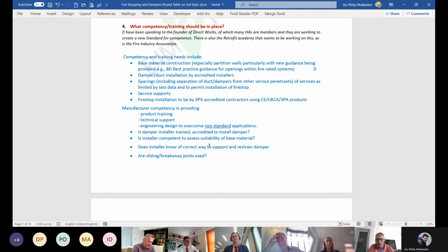That's my practical experience. So therefore, when Howell is saying that the fire stopping would be designed, presumably by an M&E consultant, that wouldn't actually work in reality, because the decision as to what pipes are going through, or exactly where that pipe is going through, would be done by not even the M&E installer. No. As you're saying, it would be the fire stopping subcontractor in conjunction with them.